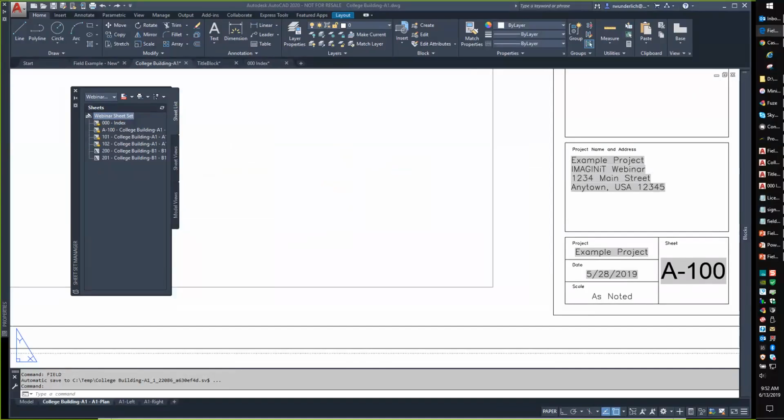Yeah, you create a custom property at the sheet set level. Add a custom property called total sheets. Give this a value that reflects the total number of sheets in your drawing. Yep, that's how we have to do it, unfortunately, is we have to know how many sheets are in there, and then we can actually go from there. Yep, it's not completely automatic.